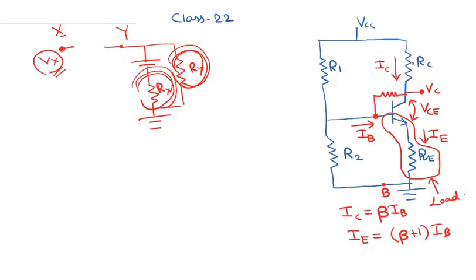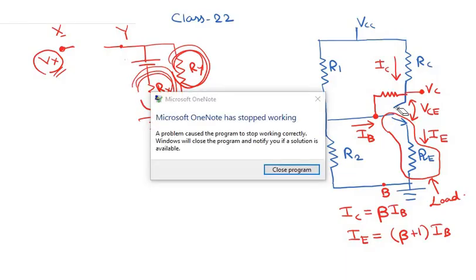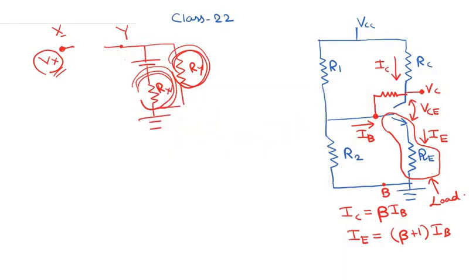So I deleted a large part of the circuit. Let me delete this base to collector junction. We have deleted this base to collector junction and replaced it with some resistor R0, where R0 has infinite magnitude, or the value of the resistance R0 is infinity. And we have to find, just as I stated, the equivalent Thevenin's network between this point A and this point B over here.